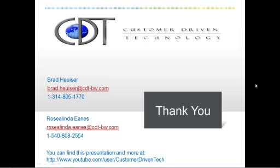And also, Brad, John asked, how can you make an existing sim rep the default rep? So for an existing rep, if you want to make it the default rep, you would just save it as the default rep. You can't save over the master rep, but you can save over the default rep. That's one thing I get a lot in my training classes: why is there a default and a master? Why do you have two that are the exact same thing? Well, that's because the default rep you can change, the master one you can't.